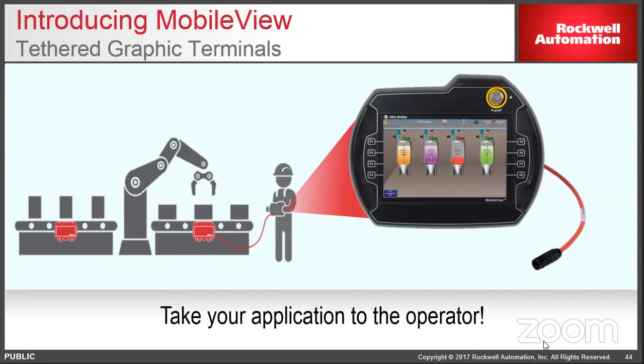So why is it handheld? It's for applications where you potentially need line of sight to a robot arm or other machinery that you want to position. You see it's got an e-stop on there. It's got a hardwired e-stop. It's got hardwired enabling devices built into the handle, sort of like a dead man switch. Once that's programmed in as part of your safety solution, you can rely on those. It's a SIL-3 solution to get back to a safe state. It's a little bit different than a normal PanelView, because usually you would have to add the buttons and e-stop to your solution. So this is all in one.